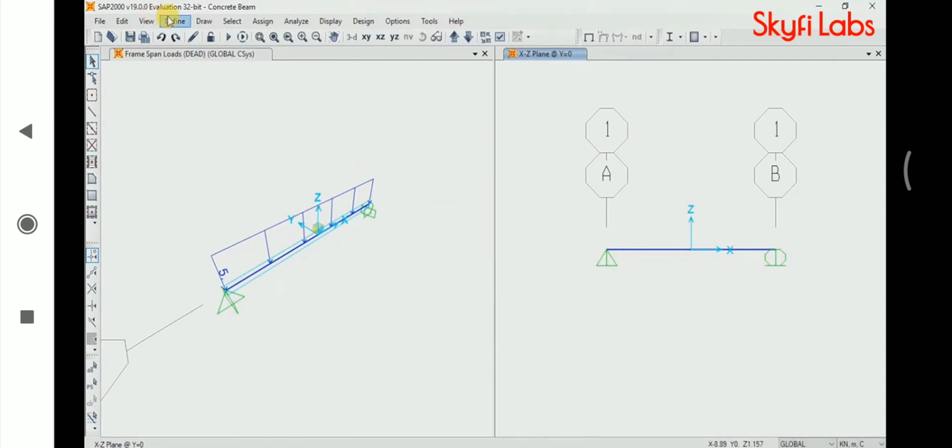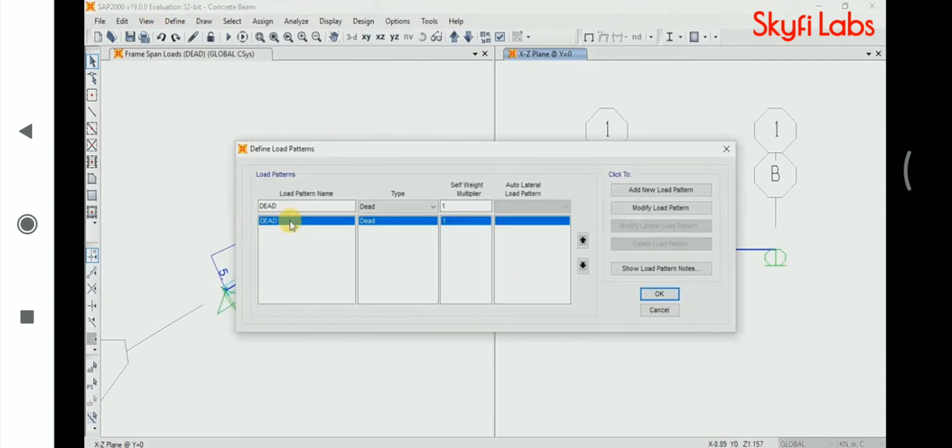Go to the Define menu, and select Load Patterns again. Now, the options are activated as you can see. In the space for self-weight multiplier, change the value from 1 to 0. Then click on Modify Load Pattern. The property of the dead load pattern has changed, and now the self-weight of the beam will not be considered while analyzing the beam.